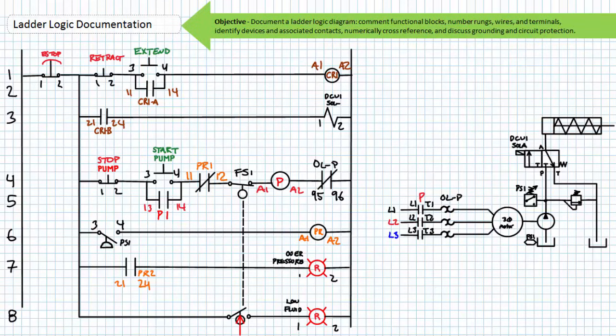Note only one arrow is necessary since this is the same float switch with two electrically separate yet mechanically interlocked sides. The normally open side of the float switch, being held closed, is assigned terminal numbers 3 to 4. The normally closed side of the float switch, being held open, is assigned terminal numbers 1 to 2. All terminals have been properly numbered for this ladder logic diagram.